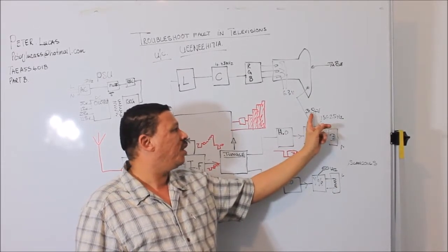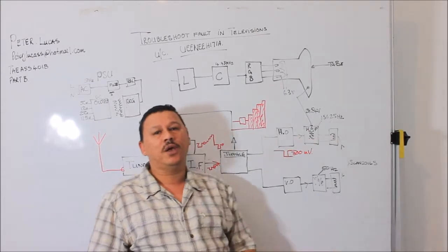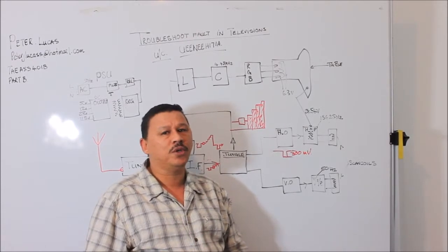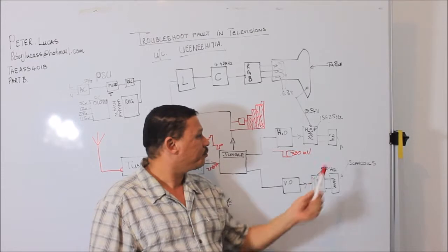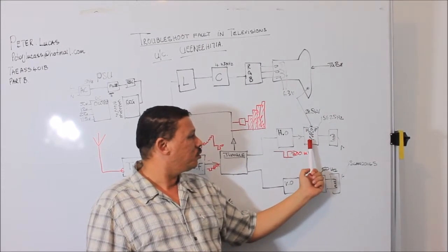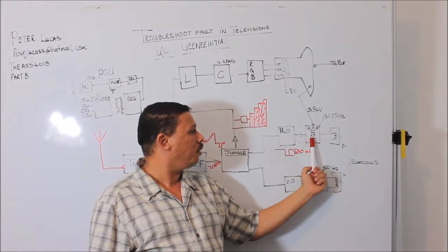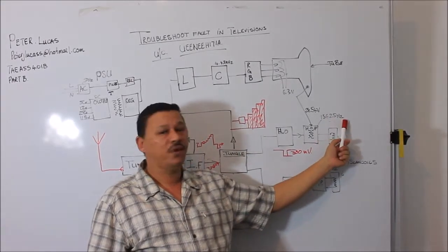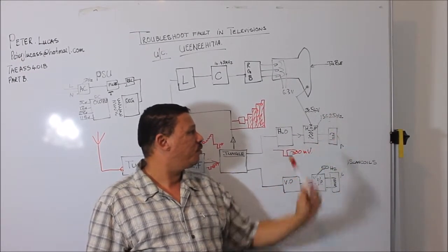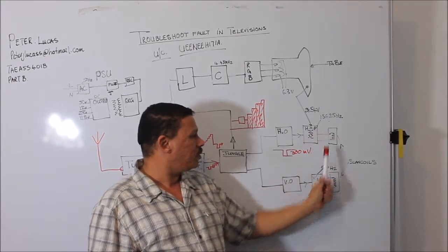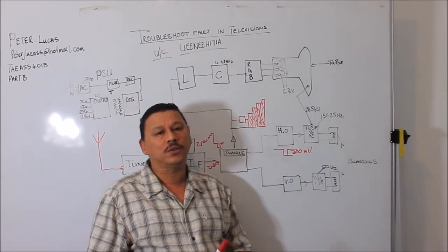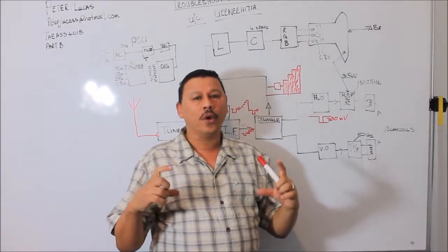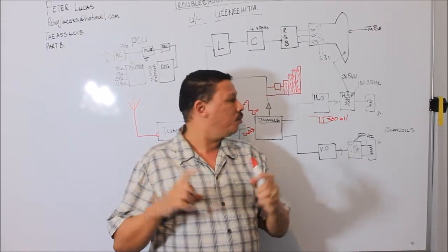After 28.5 kV, you will start getting radiation. So just be careful not to work too close to a television, especially a computer monitor that's got the old CRT tube. The frequency for the horizontal, to be able to switch this transformer on and off at a high frequency to generate this 28.5 kV, is 15.625 kilohertz. The output ends up also into what we call scan coils. The scan coils are connected around the neck of the tube. They are the two coils that are actually vertical on the tube.